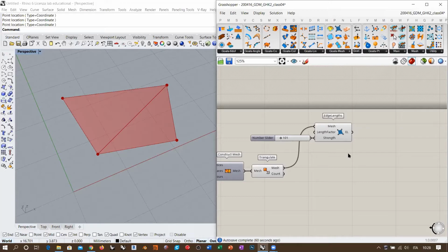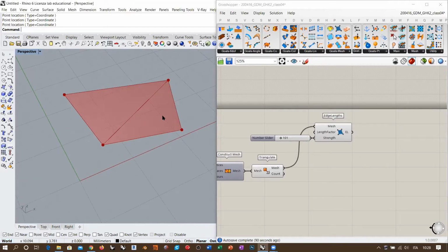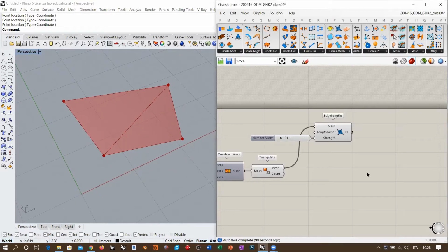The important thing is that you don't make mistakes during the definition, or you don't create forces that are producing effects that are not working in the same direction. In that case, you might have some kind of instability during the simulation, or the simulation might crash, or at least you will notice some strange behavior in your system. But anyway, in this case, it's enough to work with edge lengths.